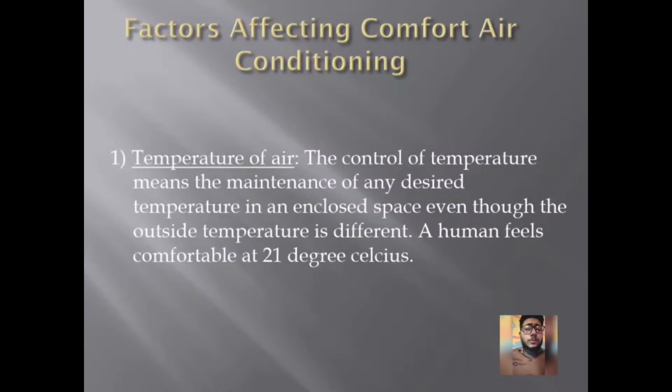When the room temperature becomes high due to heat gain, it causes human discomfort. When the room moisture becomes high, the increased humidity causes difficulty in depositing the body heat for human comfort. An indoor temperature of 20 degrees Celsius and relative humidity of 60% is quite good. Any air conditioning unit will be able to achieve the above requirement and maintain the condition for comfort.